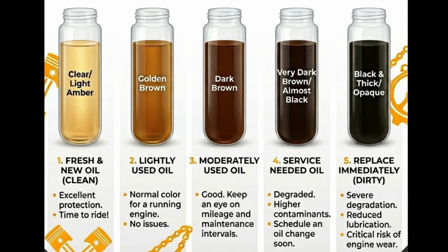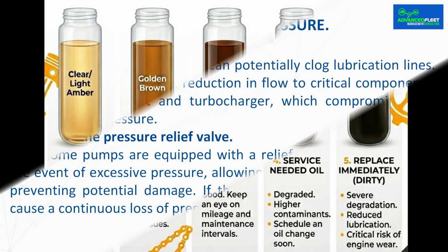Degraded or contaminated oil. Oxidation, the presence of water or metal particles, alter the viscosity and reduce the lubricant's lubricating capacity. In this context, it is crucial to adhere to oil change intervals and have oil analyses performed at accredited laboratories for vehicle fleets.